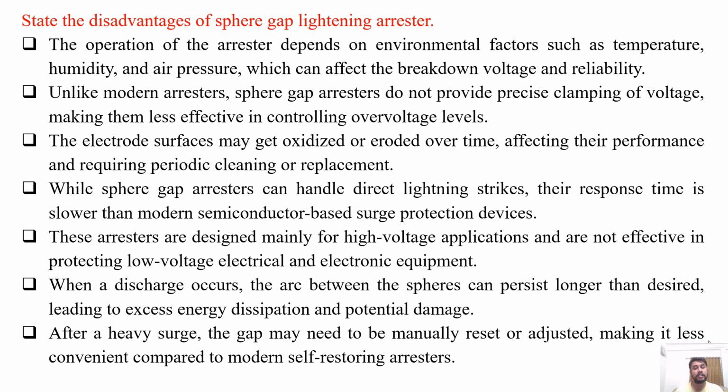These arresters are designed mainly for high voltage applications and are not effective in protecting low voltage electrical and electronic components or equipment. When a discharge occurs, the arc between spheres can persist longer than desired, leading to excess energy dissipation and potential damage to the arrestor.